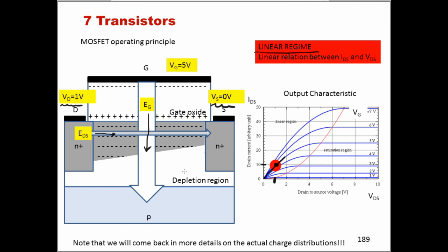And because the total electric field in the channel area is actually the combination of these two electric fields, we should expect that the free carriers that are forming the channel should readjust their spatial distribution to accommodate this new electric field that is not just directed vertically, but is now directed in a diagonal way.